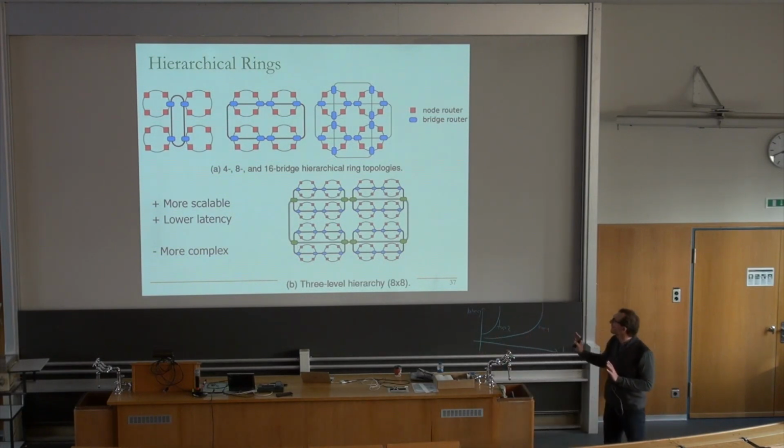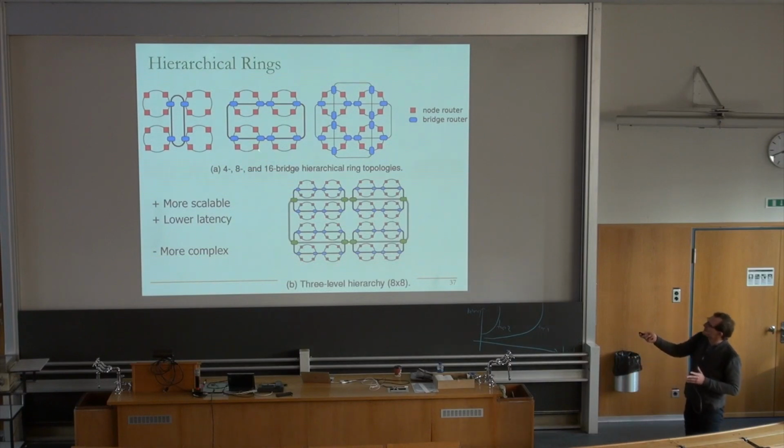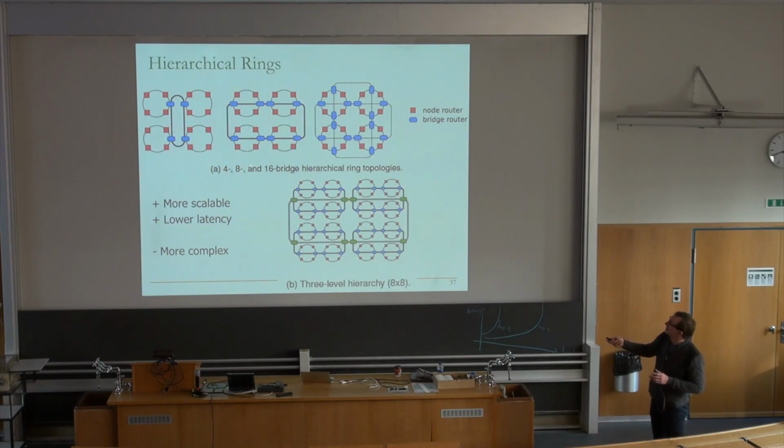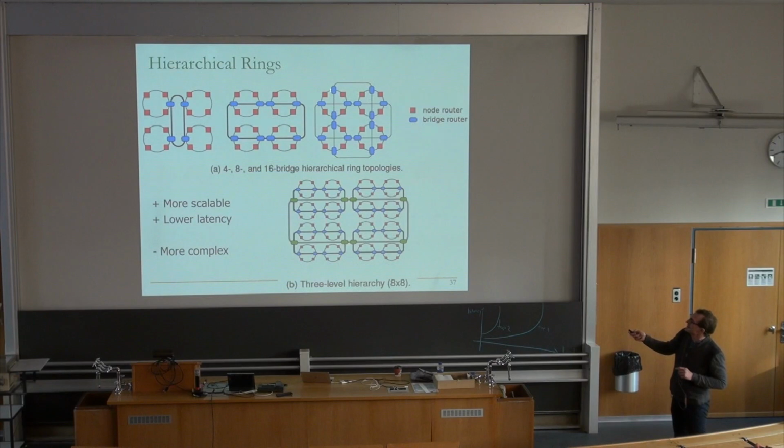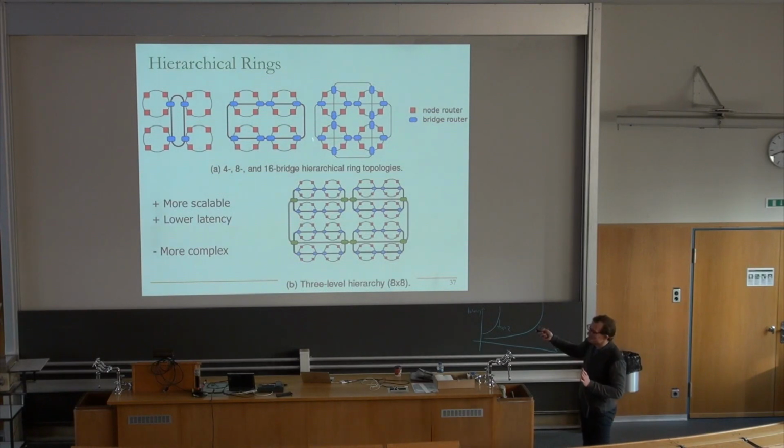It's actually beautiful, I think. And you can look at this one. This is another way of connecting these 4 local rings, each housing 4 cores. This global ring potentially has higher bandwidth, and more connections. And this is another way. Now you actually have 2 of these global rings. So depending on the contention and communication patterns, you could use this ring or this ring. Now you have to decide which ring to inject into, right? So it's beautiful. And these are also easy to route.